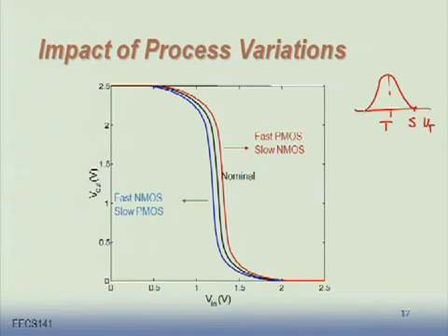And this one, when the threshold turns out to be low, the devices are going to turn out to be the fastest. And we're going to call this the fast corner. And this is engineering lingo, right? When you get a chip, they'll tell you it's typical, fast or slow. You'll figure that out easily. You power, plug in the supply, flip the switch up, and it's going to run as you have designed for a typical case, or slower or faster.